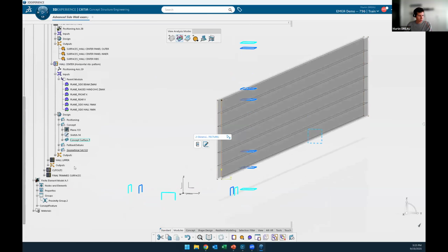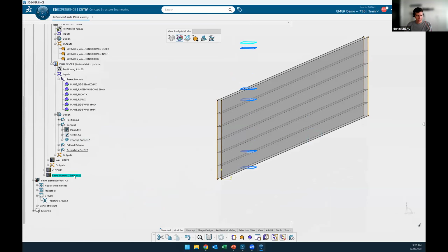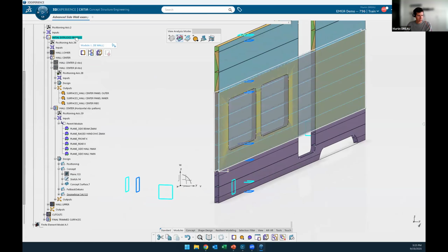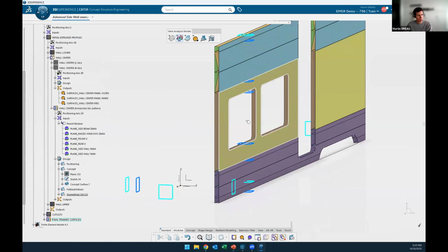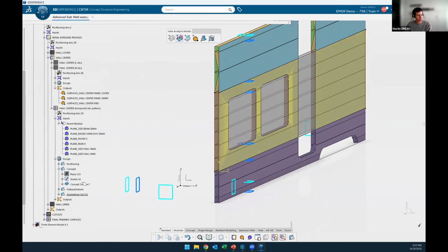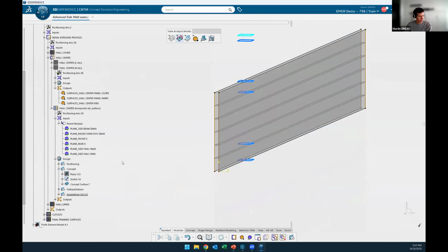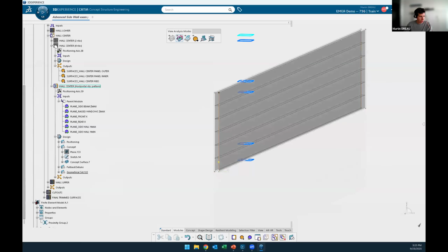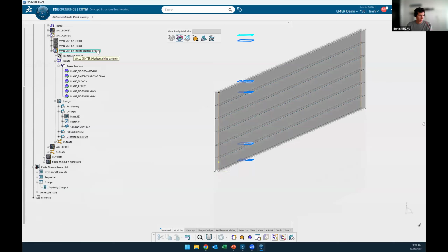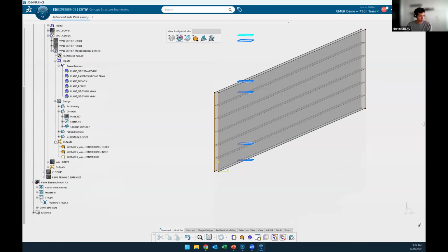Right now, let's have a look at our final trim surfaces. So if I hide the X3D profile, we see again, like before, we don't see the ribs yet. It's normal. We haven't updated the interfaces, so we will do it. So in the module I'm currently working on, wall center horizontal ribs pattern alternative, I open the output.